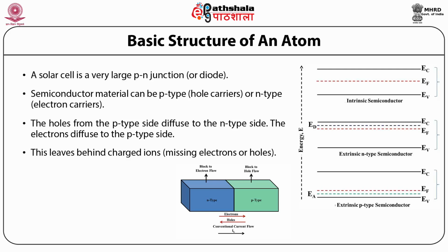When a PN junction is illuminated, excess electron-hole pairs are generated by the light in the semiconductor. The inherent asymmetry of the PN junction diode encourages the flow of generated electrons from P-type region to the N-type region, and the flow of holes in the opposite direction.